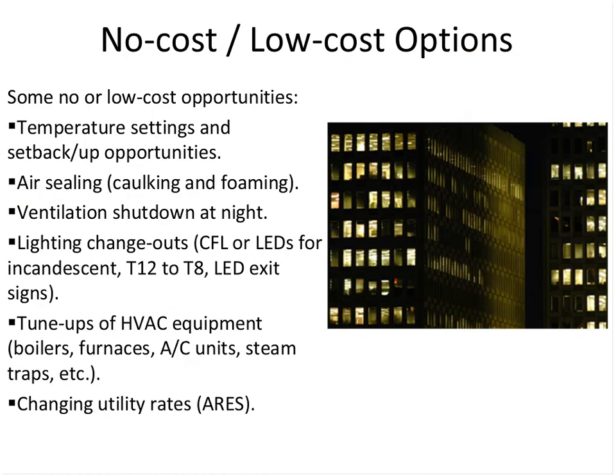So some other things to check for in the building: the temperature settings and whether or not they do setups or setbacks in the building. Air sealing and caulking. Go in the building on a windy day. You can see if you can feel air coming into the building anywhere. So there's an opportunity for caulking and foaming and sealing that building up.